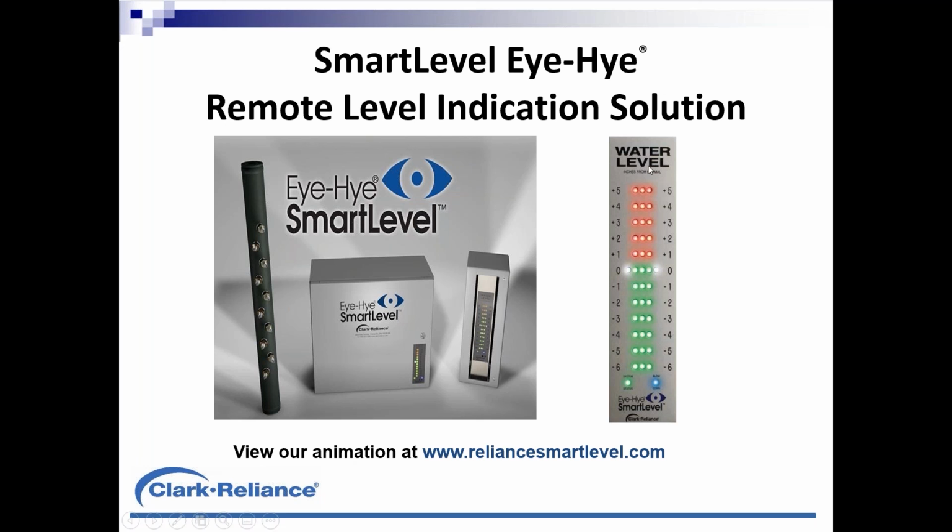For our conductivity probe device, for 7 years now, we've had a SmartLevel, as we call it. This instrument was improved where we have a microprocessor, independent one for each probe level, and we have a blue warning light that alerts the operator before you get a false signal that the sensors are beginning to get contaminated. It works much like a check engine light in your automobile, as well as all these LEDs now protrude out the front of the indicator to provide full 180-degree viewing from the surface of this panel.